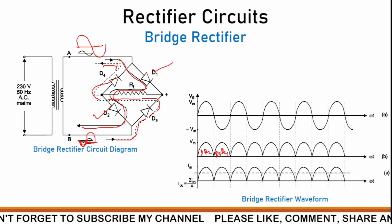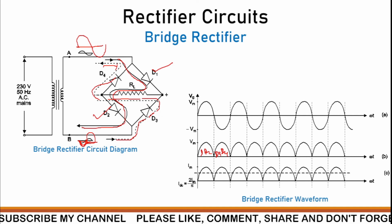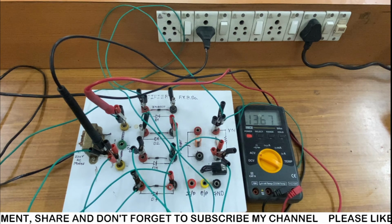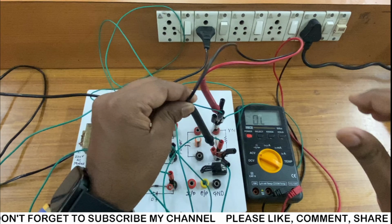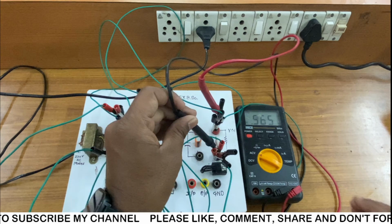So how to calculate the ripple factor of this particular circuit? Just look in here. So let's look. I have connected the 4 diodes. This is a bridge rectifier. I have measured the AC at input. You can note down the AC at input. Then I am going to measure, for the ripple factor, the value of AC at the output.